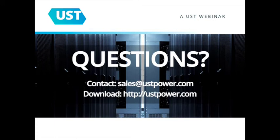Another question, do you consider consumption reductions with reduced voltages in your business case analysis? In this white paper, we did not. We considered simply the improved efficiency, and if we would have considered that, the improvement would be for every 1% of voltage reduction, you're going to get a 0.5 to 1% consumption reduction.